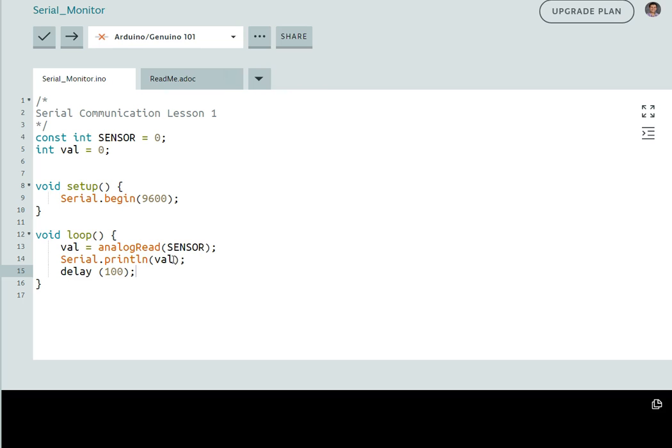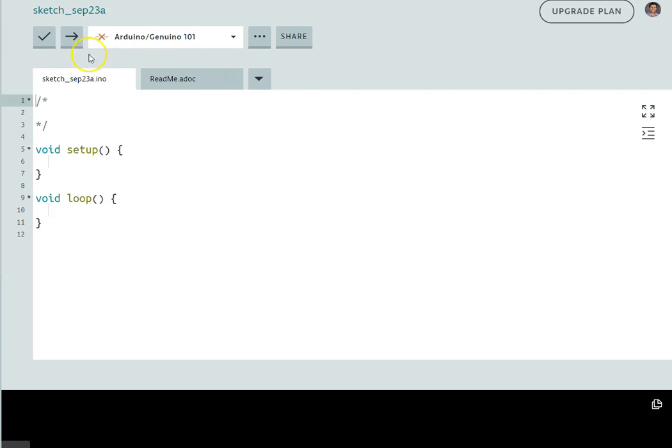Now we can have some fun with this if we wanted to. So now that we have this, we kind of understand what's going on, but just to understand how serial communication works as well, we can do a new sketch. All right, and I'm just going to show you how this can work for other things. So we could actually send secret messages if we wanted to with our Arduino, where people could plug it in and it reads it. So we can do serial.begin.